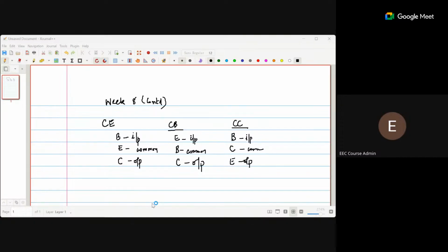Now, moving to the small signal analysis, right now we are going to design the amplifier. This biasing helps us to set the DC voltages and DC currents in the circuit. Now, if we are considering the common emitter configuration, to the base terminal we are going to feed the AC signal, the small signal. The amplified version of that we need at the output.